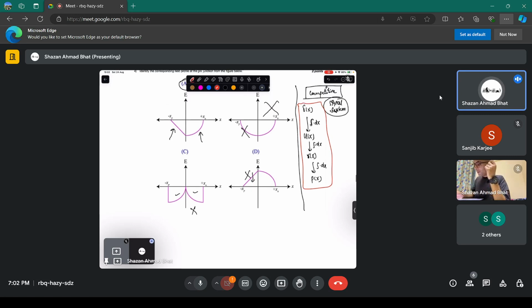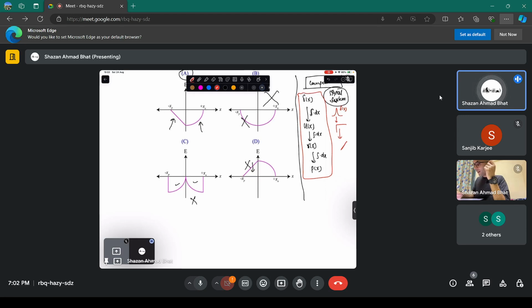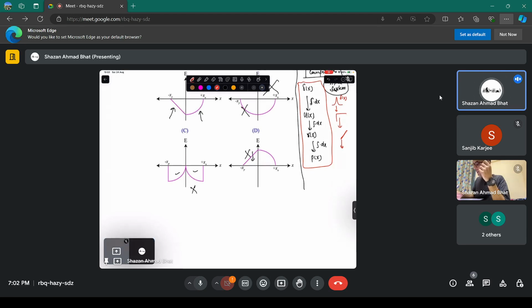Now, that means if you have a delta function, a delta doping, and you find its electric field, it's going to look something like this, a uniform field. If you have a uniform doping, and you find its electric field, you're going to get a ramp. If you have a ramp in doping density, if you integrate it, you're going to get a parabola. Simple as that.